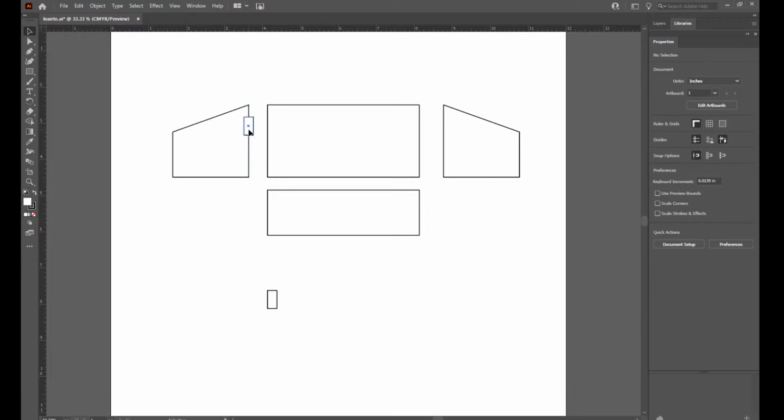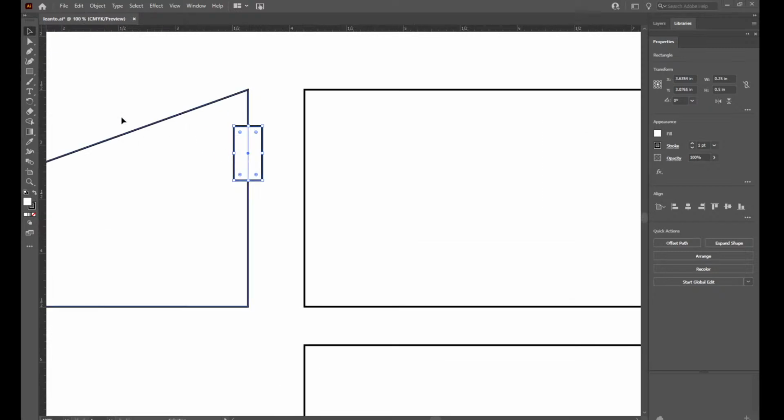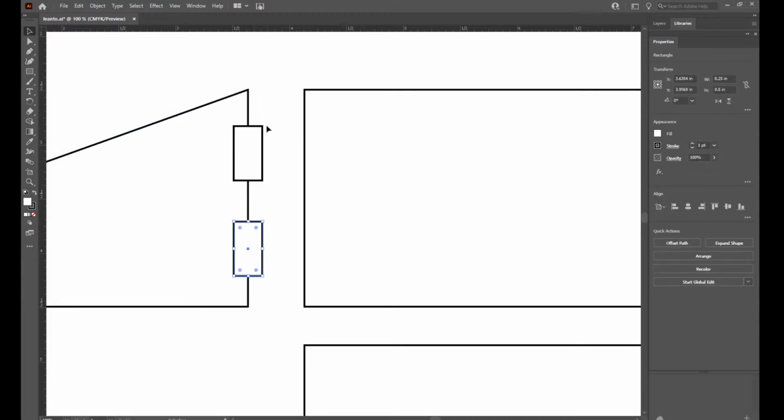It's much more convenient. So we're going to select this shape, and with the selection tool on, we're going to hold Alt and drag the center point down onto the center of the line and have these two overlapping in the midpoint of the rectangle. Okay, these are going to be notches. So we're going to hold shift when you select the first one. Now you have two of them selected. And now hold Alt and drag this horizontally across.